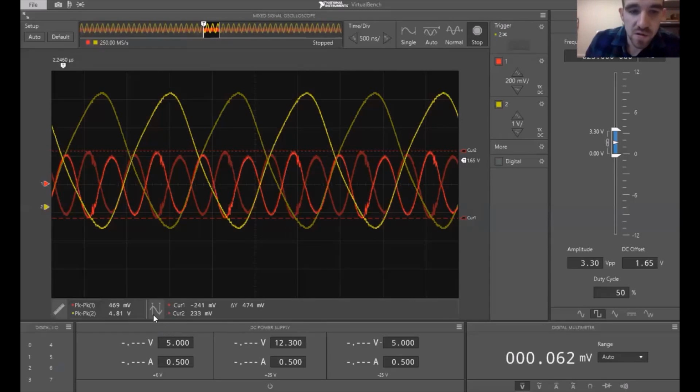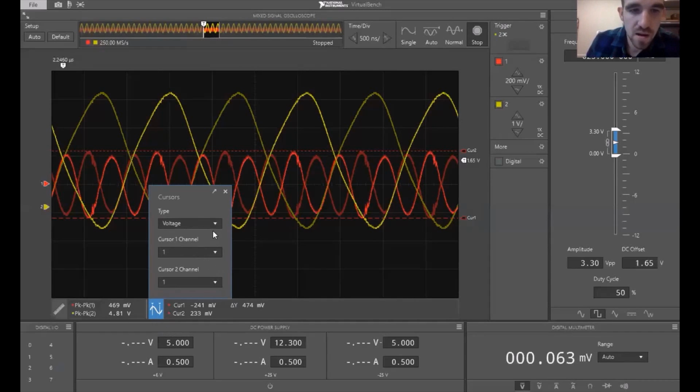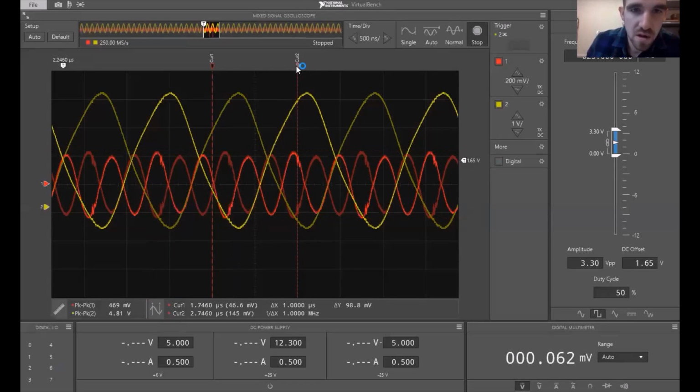And if I want to measure the time, I'll measure the time, cursor 1, and measure the eye width, which I get 270.29 nanoseconds, which basically shows you that as you go down the line, again, the eye height decreases and the eye width decreases as well. And you see here in comparison to the last one, the number of harmonics increase as well.